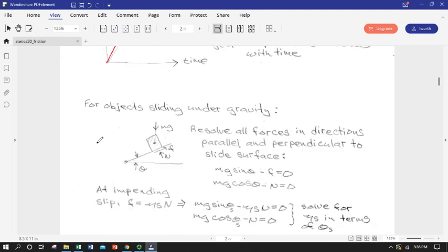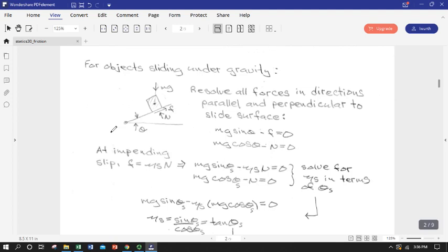There are some special relationships that we can define with that definition of imminent slip for friction force and just our plain old equations of equilibrium, and these are used in geotechnical applications quite a bit, and that is called the friction angle, and it's literally another way of describing the static coefficient of friction.